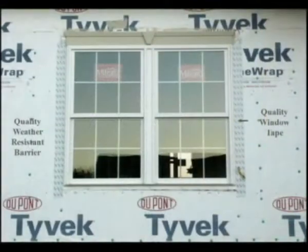Again, I don't want to go into too much detail on building design and construction, but just showing you right here how you can make an airtight home by using the proper sealants. In this case, we use a window tape around the window. Making sure that you get a good quality seal there so you don't have air infiltration around there.